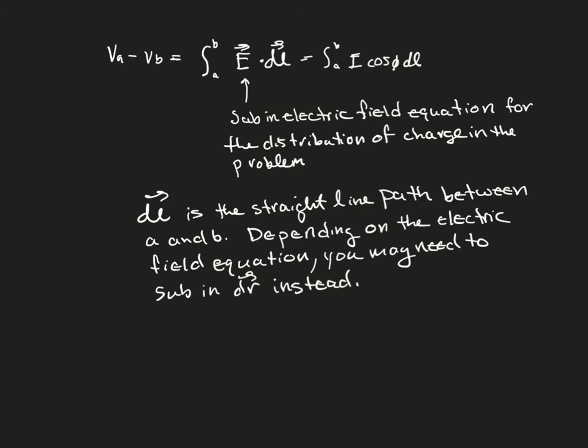So you have to make sure that this L matches up with the same variable in your electric field equation. And this equation is going to become very important in topic 24 as we begin to calculate capacitance, actually. This is how we determine how to calculate capacitance, believe it or not.